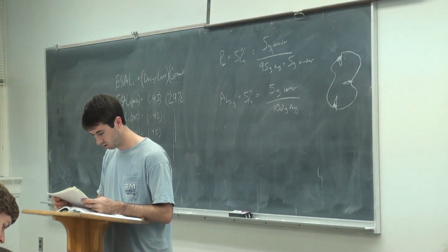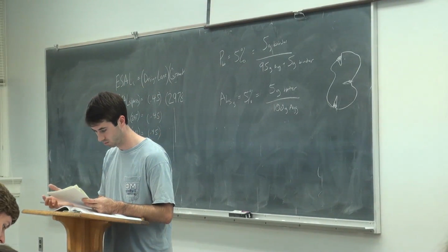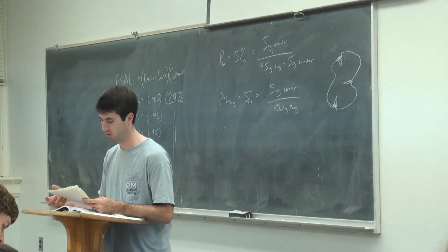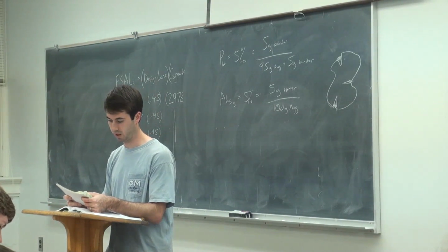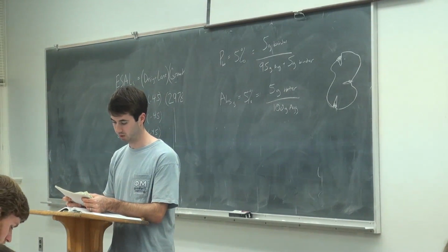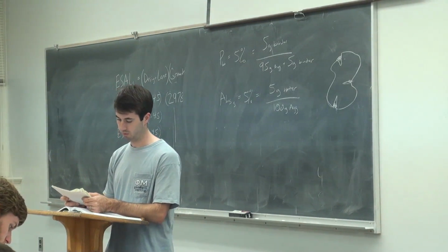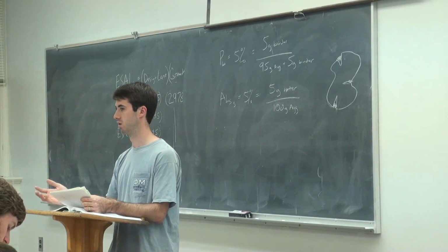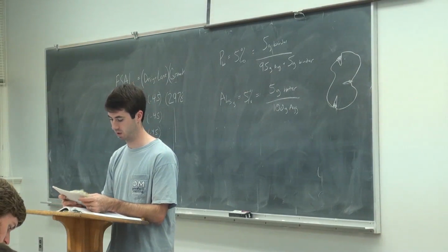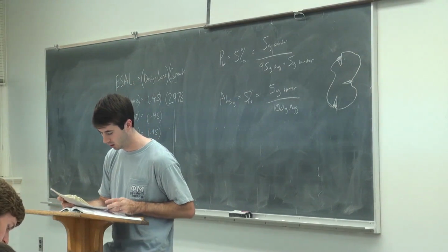The control points, I mean, basically just whatever the gradation curve has to stay between those points. So for 9.5 nominal max mix, your 9.5 millimeter size, you have to have between 90 and 100% of that aggregate for it to be classified. It's got to go through all those points.